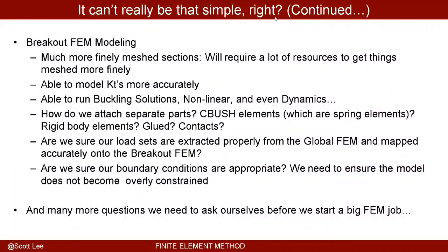So as I move on, these finely meshed sections require a lot more resources because it's a lot more labor intensive when you have to finely mesh things. As I mentioned already, KT, stress concentration areas, it takes more resources to model those more accurately. With these finer breakout FEMs, we can run more complex solutions like buckling solutions, nonlinear solutions, and dynamics. We're not just running solution 101 linear static. We can run other, more involved solutions.